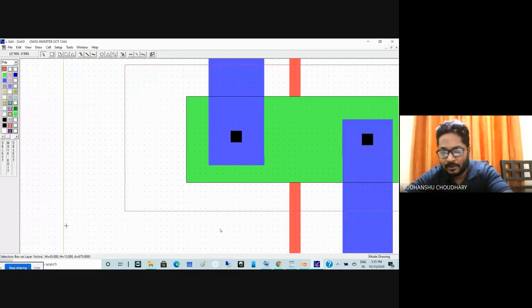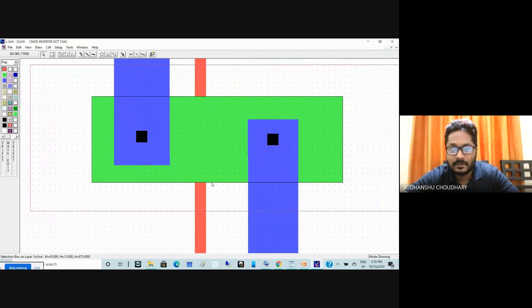Yeah. So the drain is on this side. Okay, this is my drain here. And the perimeter of drain will be calculated by measuring this side, okay, and this side, right? So you add up these 3 dimensions, that is from here to here, and from here to here, and then from here to here. Okay. Now this dimension is not added in calculating the perimeter, that is the dimension which is towards the gate. So that is not considered while calculating the perimeter of the drain or source region. So only 3 dimensions, that is this dimension plus this dimension and plus this dimension. So let us see what are they.